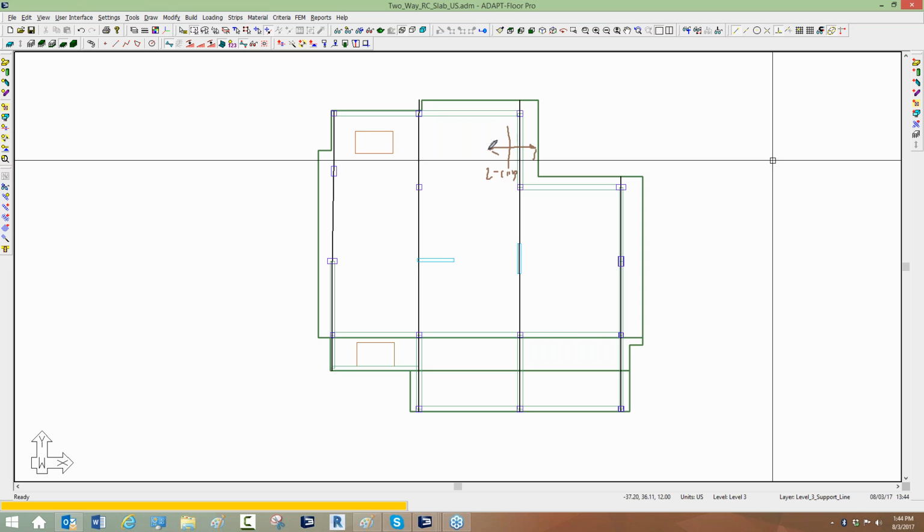Okay, and you say, well, that's weird because the bottom should be at the bottom of a beam. The section really looks like this, and the user says, well, do these bottom bars go here or do they go down here? Okay, so whenever you have a design cut which intercepts a beam like this one, then the bottom bars are always to be placed at the lowest effective depth of the beam of the section, which is here, not here.